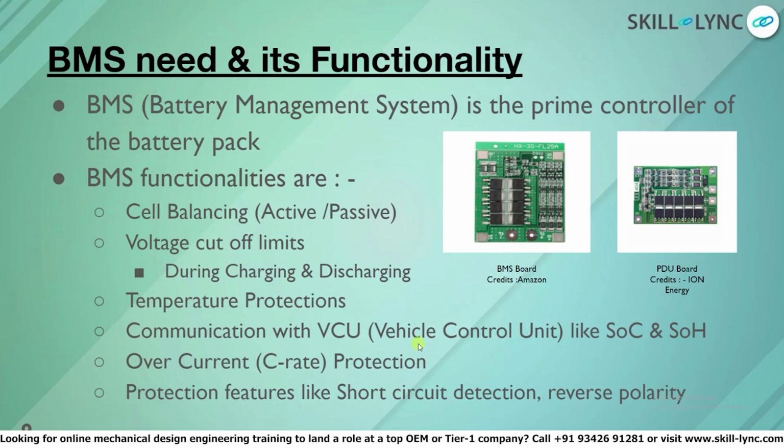So this is all monitored by the BMS, which means the BMS becomes the vital component of the whole battery pack, which has to be programmed correctly, so that all these precautions and safety are considered in the BMS functionality. So now, one of the major functionalities of the BMS, that is cell balancing. So let us discuss cell balancing.